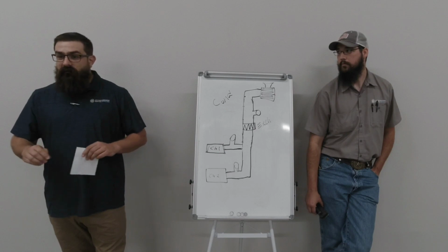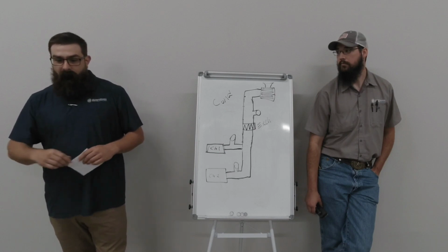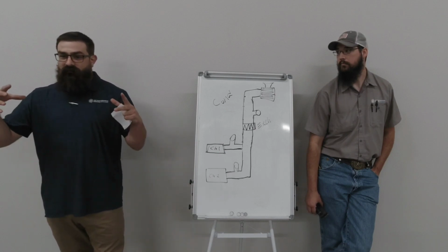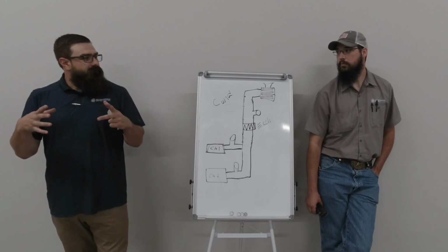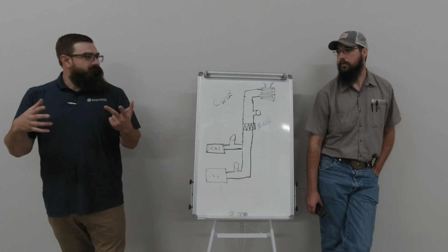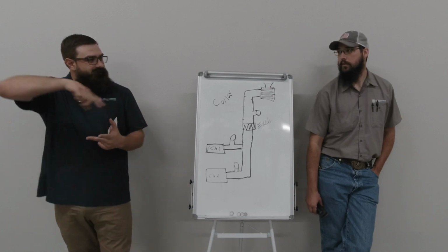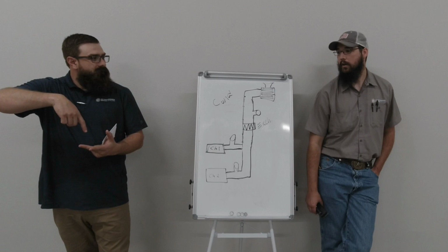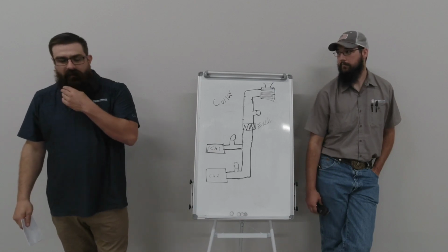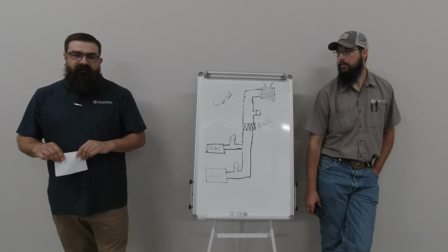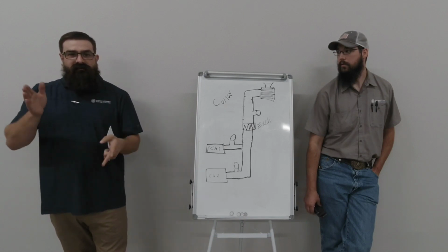If your pressures are really equal, then you may have a bust in one of the lines and it's going through, because those things are jacketed a lot, aren't they? Which ones? Condenser coils. Aren't they usually jacketed with the spiral coil through it? Well, it'll be a tube in tube most of the time. Okay. Yeah, I was just thinking, what would cause more equal pressures across the two?